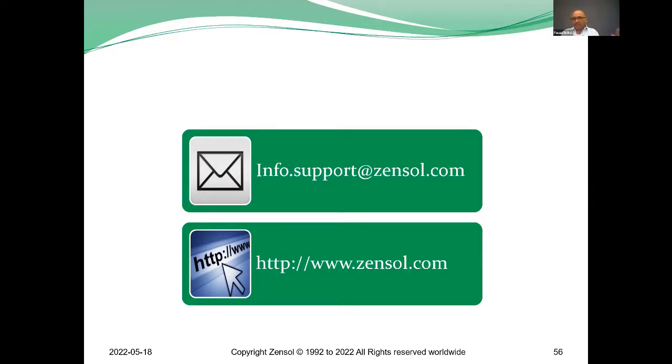Phases A, B, and C must be the same if you have the same breakers. And second, when you use a family of breakers, it's in general always the same signature. So you have two references: one with the other phases, and the other signature with the family, the same brand, same model.